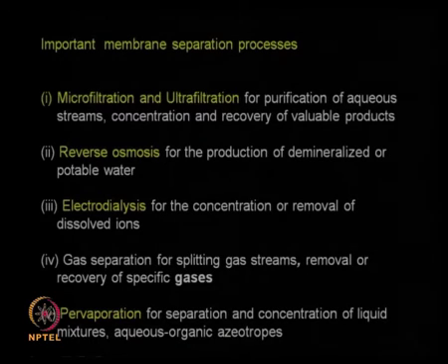So we can use membranes which are hydrophilic, so the water alone can be just removed from ethanol, so the ethanol can be concentrated to 100%. So pervaporation is used in such situations. Sometimes you want to concentrate fruit juices, you do not want to heat it because fruit juice will lose its flavor, texture, color, so there you use pervaporation. So in such situations pervaporation has become very useful.